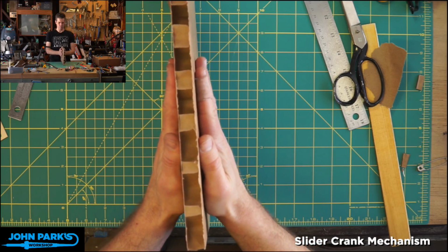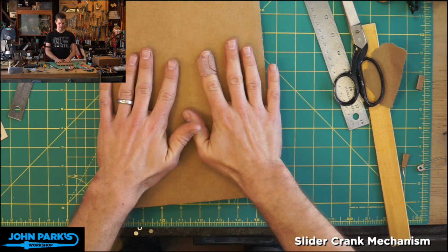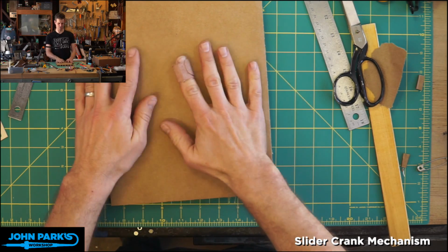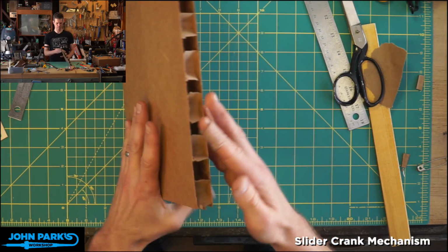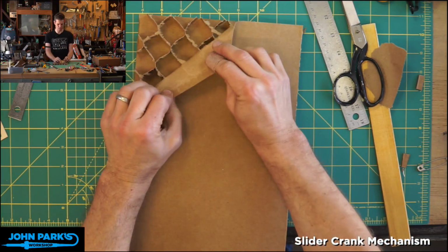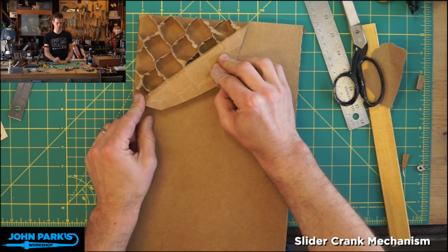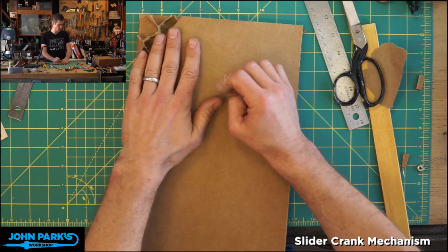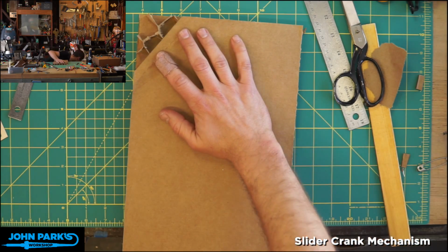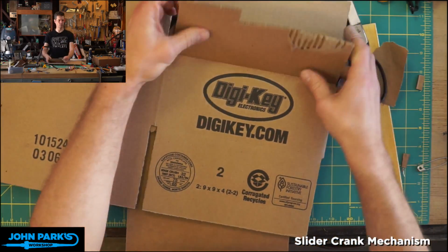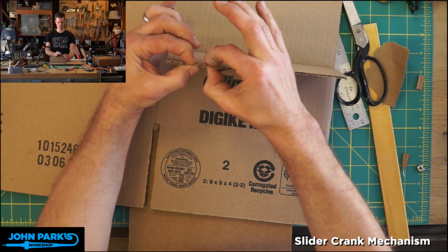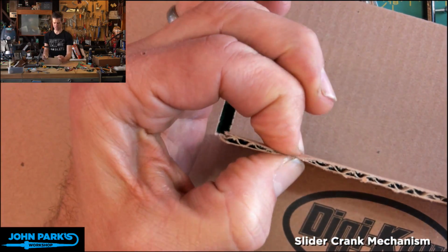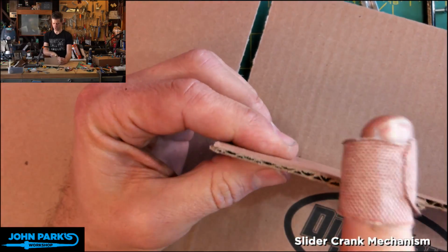This is interesting because the flutes are actually oriented in this axis, what I'd consider kind of a y-axis in a 3D coordinate system, instead of along the x-axis. So if we peel off some, you'll see there's flutes, kind of almost like a honeycomb thing, that give this a strong compression strength, which is not the case with our more typical corrugation. If you try to pinch or compress this, it compresses very easily. So you can see the compression of the flutes. It's dead easy in this axis, very difficult pushing down on it.